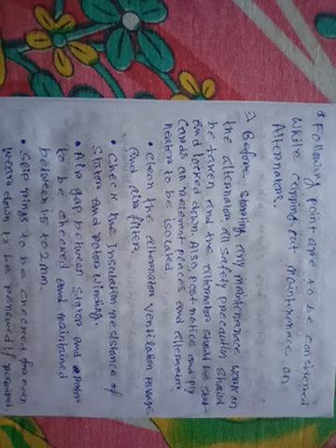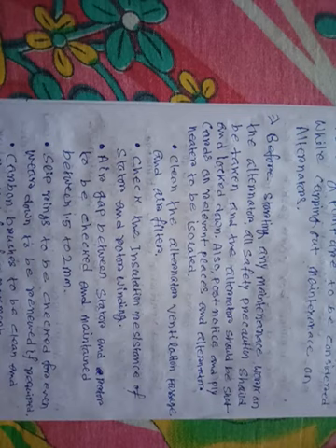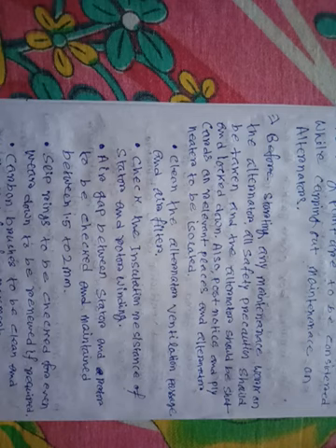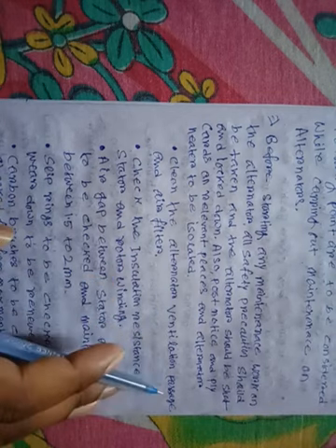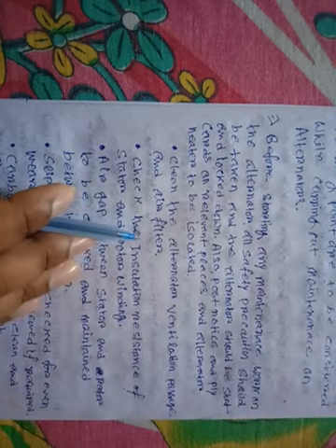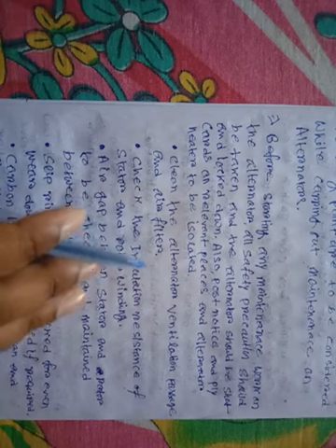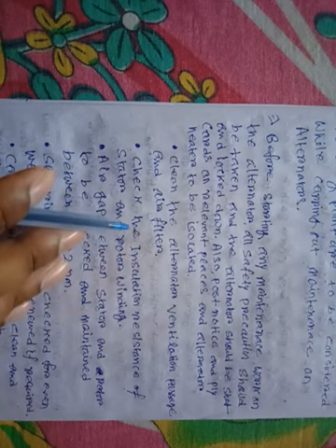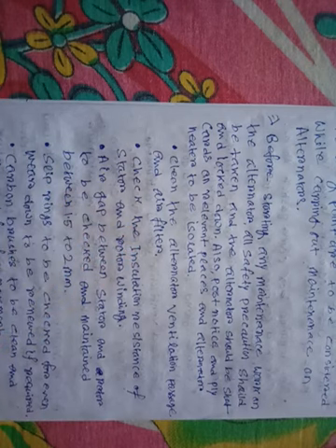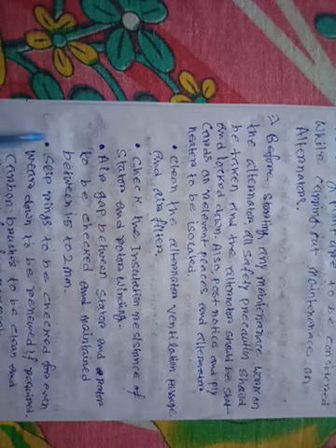Some points are noted here for the clearance for the maintenance of the alternator. First point is clean the alternator ventilation passage and air filter. The air filter or ventilation is provided to the alternator for releasing heat into the atmosphere when the alternator increases its temperature.